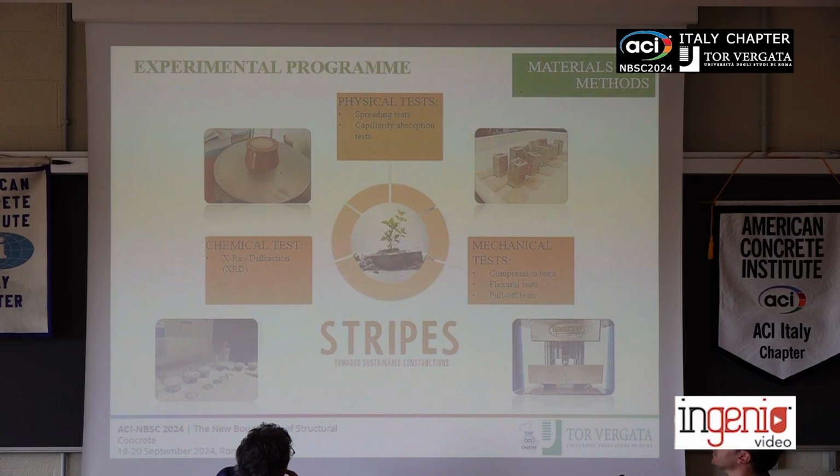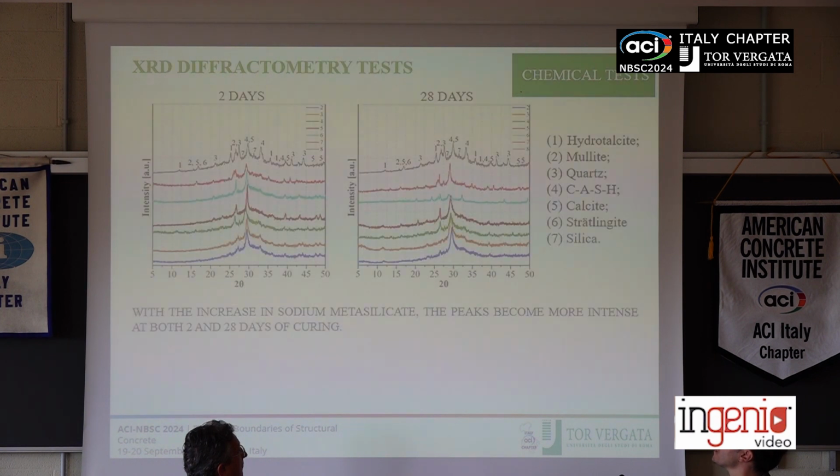Regarding the mineralogical analysis, we performed X-ray diffraction test to characterize the several phases that belong to the mortar. Regarding the physical properties, both spreading test and capillarity absorption test were performed. And finally, mechanical test, we evaluated the compressive and flexural properties of the mortar in the hardened state, and also pull-off test to evaluate the bond between the mortar and the substrate.